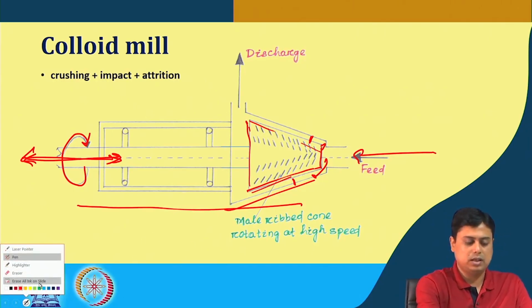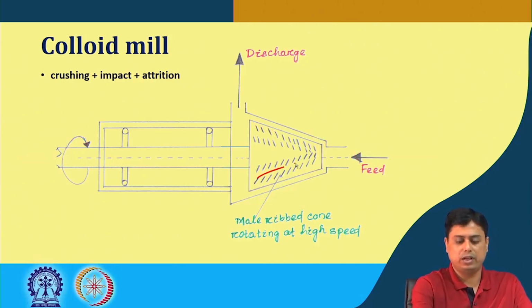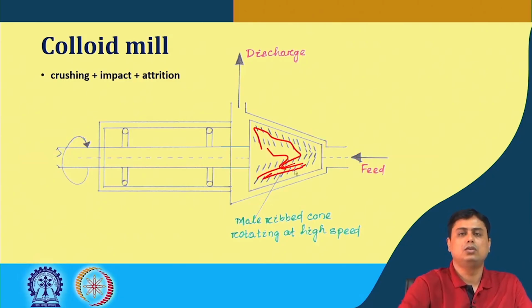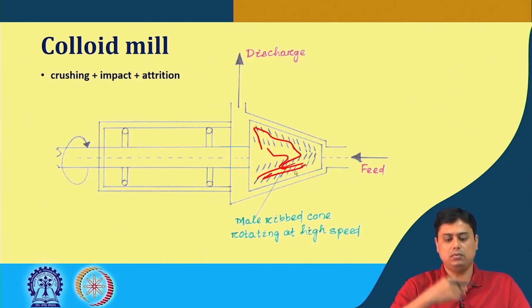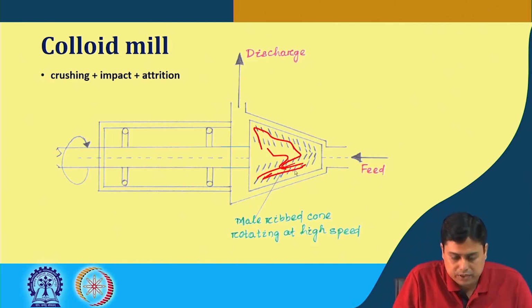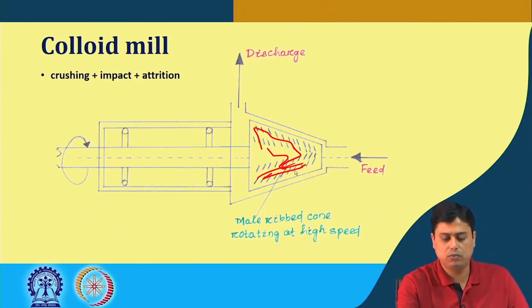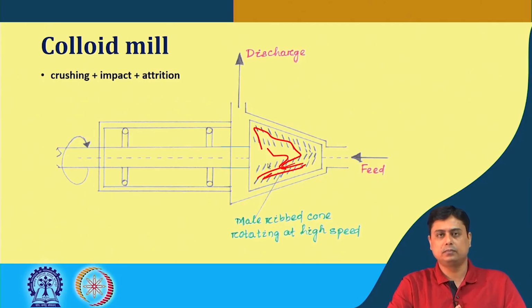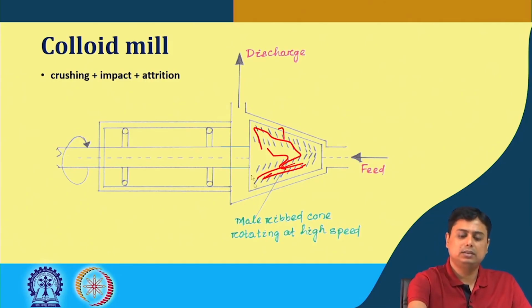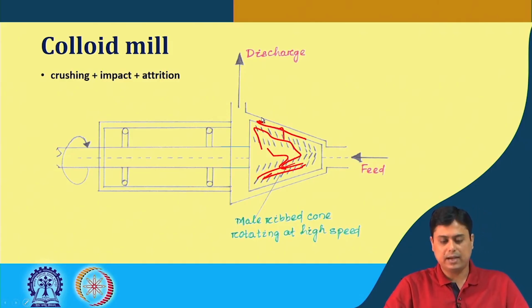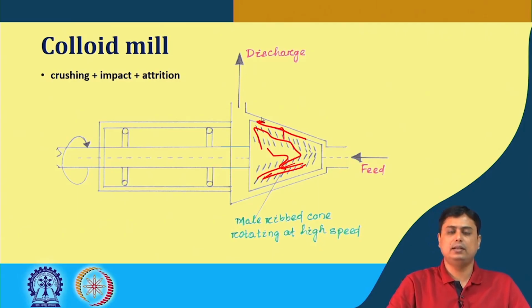On this side we have this grooved section, so that if the friction coefficient is higher, it can create a higher resistance to the flow of the feed, so that it can have a higher residence time. Within that time it crushes the particles, and this gap between the static wall and this spindle head dictates the discharge size.